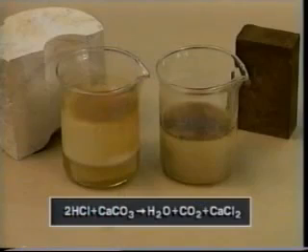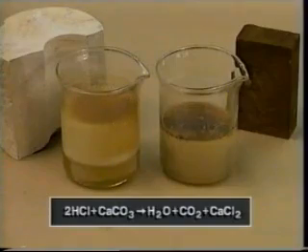Hydrochloric acid is available in concentrations as high as 35% by weight. Concentrations above 28% are not used in practice. In fact, concentrations above 15% were not used until recently, when inhibitors could successfully protect the equipment and tubulars against excessive corrosion. Common HCl concentrations used today are 7.5%, 15%, and 28%, with other concentrations available upon request prior to mixing. Hydrochloric acid produces very few harmful byproducts when reacting with matrix minerals in most carbonate formations.